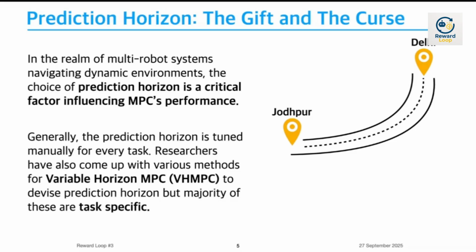The problem with this is, suppose your experiment required many more steps than the maximum value of the prediction horizon. Say, if you started with a maximum prediction horizon of 50, but your task required 200 steps, then at the 51st step, your prediction horizon has been reduced to 1. Now, if it has been reduced to 1, it does not encapsulate the advantage of MPC. The controller is now nothing more than a PID controller. So what is the advantage of using MPC then?